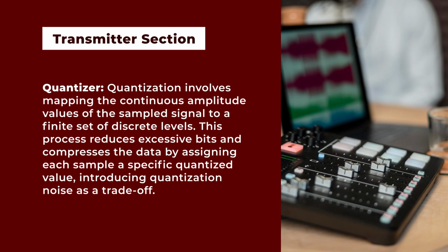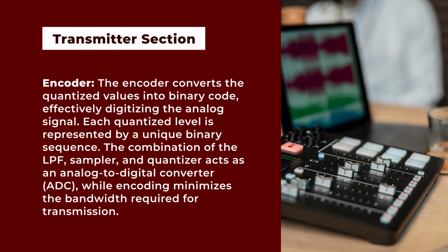Another important part is the quantizer. Quantization involves mapping the continuous amplitude values of the sampled signal to a finite set of discrete levels. This process reduces excessive bits and compresses the data by assigning each sample a specific quantized value, introducing quantization noise as a trade-off.